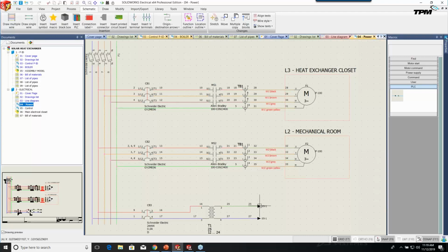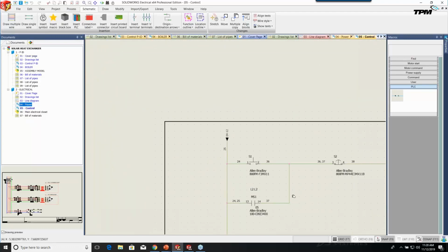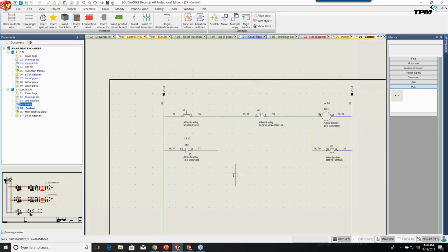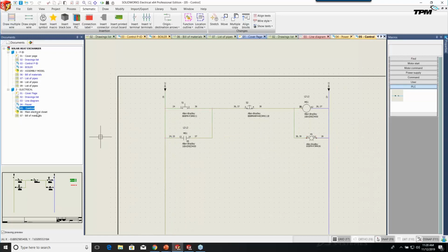As you migrate through these projects, just know this, we have a lot of built-in hyperlink information, so we can get around here pretty quickly. When you're getting into these from and to arrows, I just simply click it and tell it to go to the next one, and you'll see it takes me to wherever in this project that circuit continues. So I'm not searching for data like I used to. I'm not asking or taking the time of people who built these drawings. I'm able to do this by myself and not bother anyone and understand fully what I'm looking at here. So very helpful just in that case. And then of course our last one was the slash sheet, which was the controls.